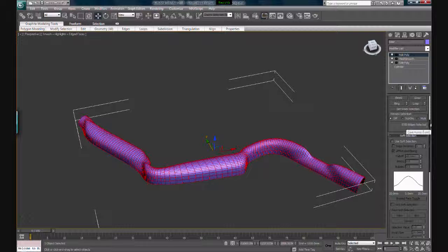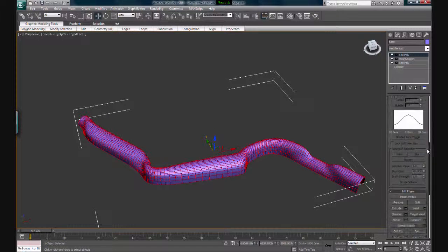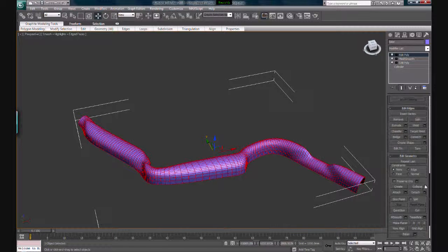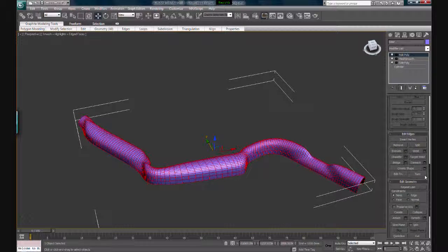The way to do it is by going down in the menu, just run down and find an option called create shape, this one here. Click on the little box next to it and choose linear instead of smooth. Maybe you're going to name it structure. Press OK.